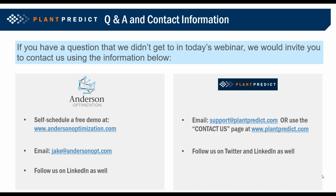So on the map builder, at the very bottom of the parameters page, you can specify north-south and east-west road width. And if you do take one of those to 0, we will combine the arrays. We refer to that as a corridor style design, which some developers use, where they just have an east-west corridor and they don't actually have the north-south roads. You can do that just by putting 0 in the north-south road space.